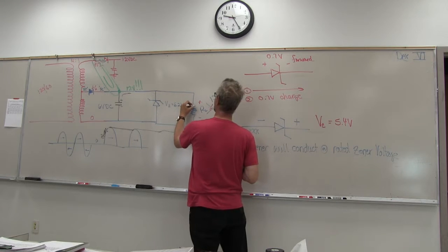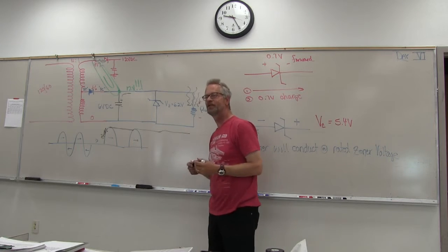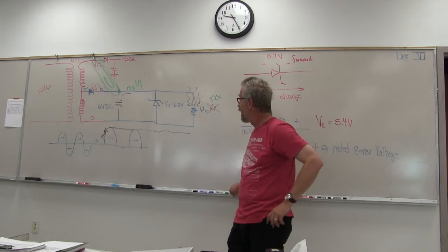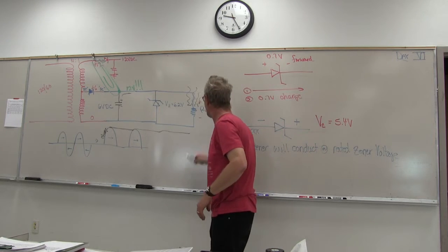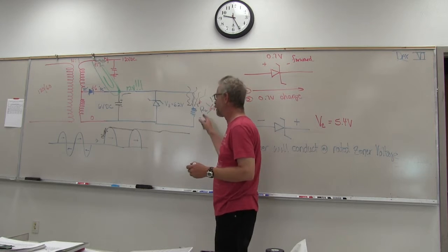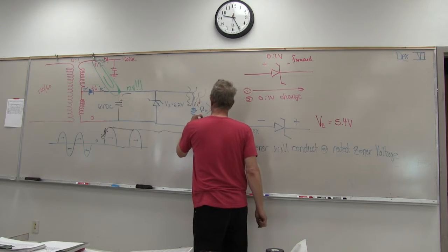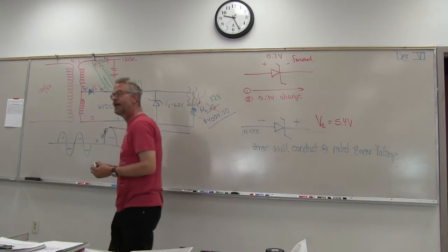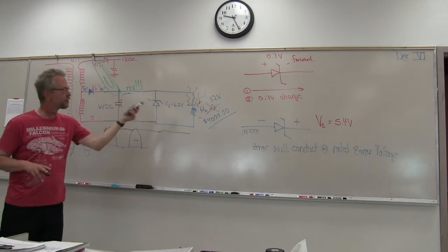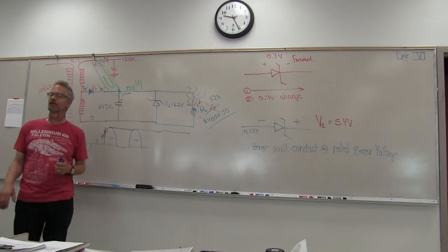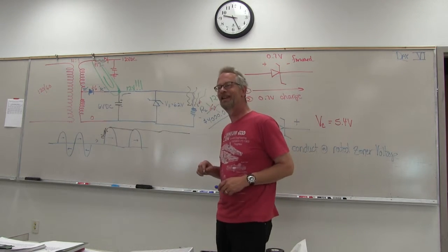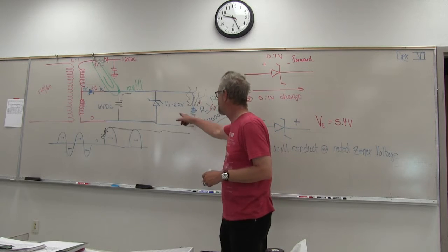And that, in many cases, would do what? Let the smoke out. Once you let the smoke out, the part's no good anymore. And the bad news is that this load resistor, even though we represent it as a squiggly line, is actually some kind of equipment. It's $4,000 to buy it. It's an expensive component. And we just fried it because some moron dropped a paper clip in the circuit somewhere else. But fortunately, we didn't, because we had the wherewithal to put in a Zener diode.